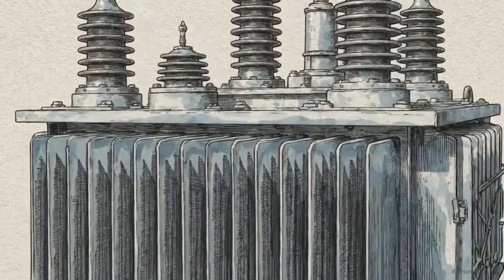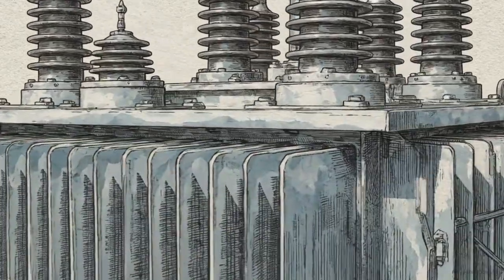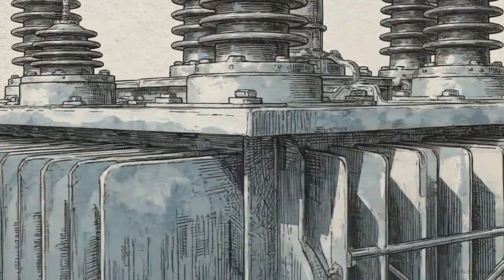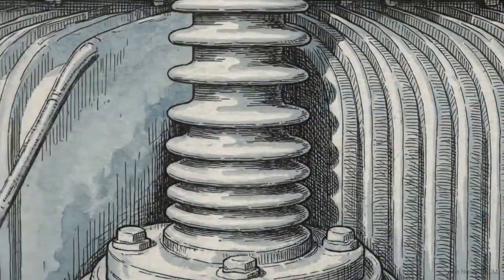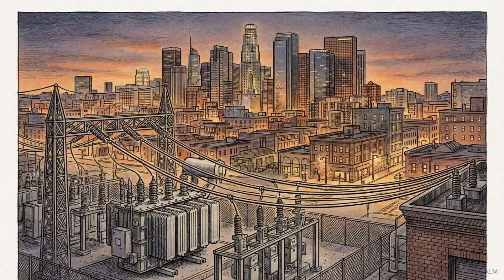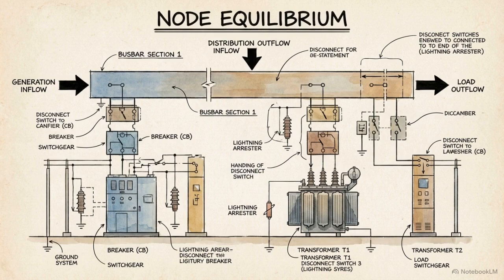A power transformer is often the most expensive and critical asset in a substation grid. It provides the essential interface between high-voltage transmission and the local distribution networks that power industry and homes. The standard method for guarding an asset like this is differential protection.